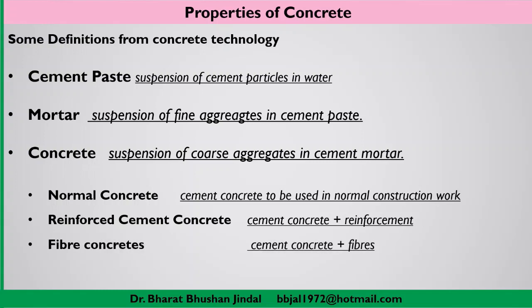Then another special type of concrete is fiber reinforced concrete. You can say it is FRC basically. So here what we are doing, we are using additionally some fibrous material. Fiber may be of many types. They may be of steel fiber or polypropylene fiber or any type of fibrous material. So what we are doing here, we are adding fiber to the cement concrete.